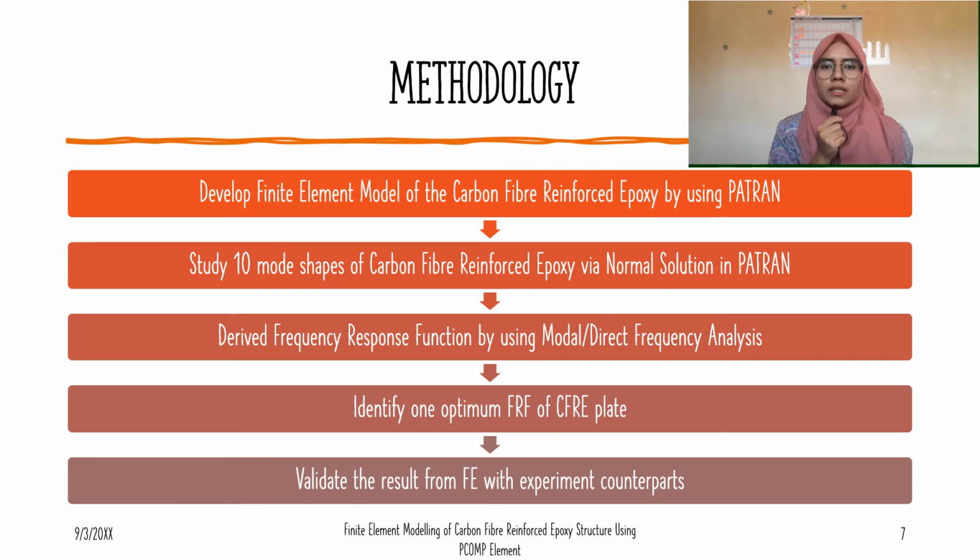Now, let's move to the methodology of the project. The first step is to develop the FE model of carbon fiber reinforced epoxy structure by using MSC PATRAN. Second, only the first 10 modes of the carbon fiber reinforced epoxy structure will be studied via normal modes solution. At this step, we will see the natural frequencies and mode shapes of the composite plate.